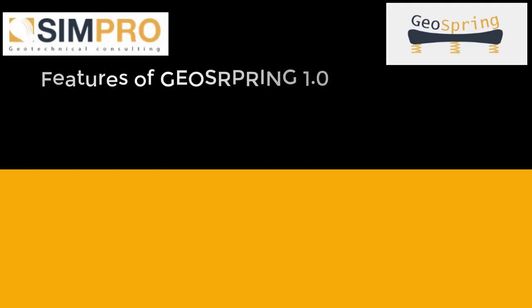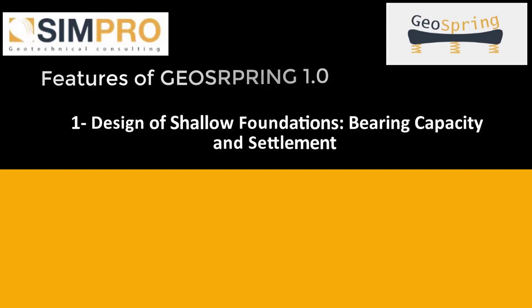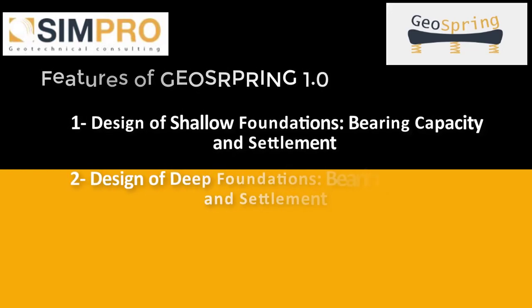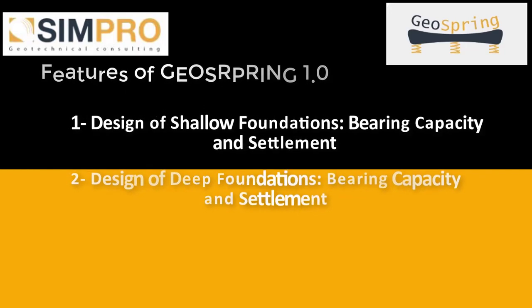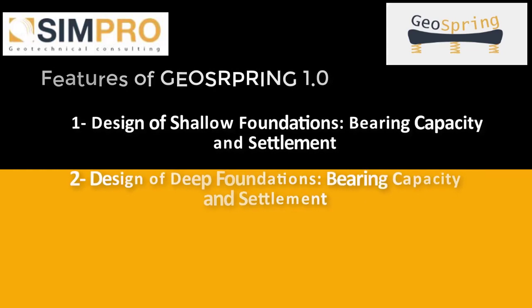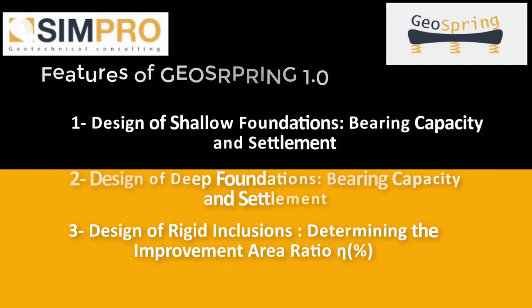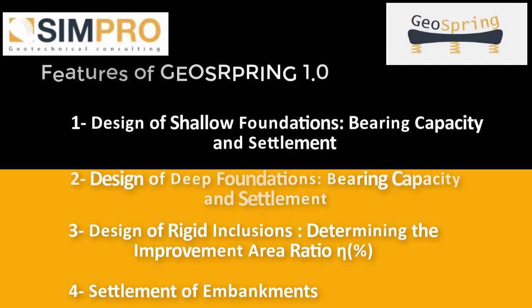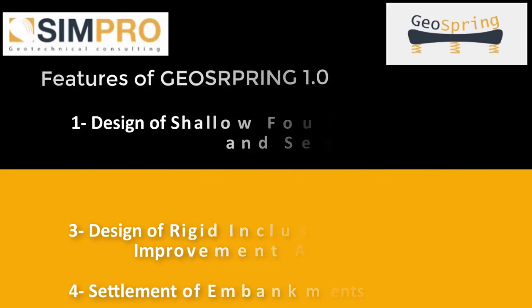Let's go ahead. Basically, GeoSpring contains 4 modules. The first module is about the design of shallow and deep foundations. It computes the bearing capacity and settlement. The second module is about pile foundations. It computes the settlement of pile foundations, single piles and groups of piles also. The third module is about the design of rigid enclosures. And the final module is about the settlement of embankments, the short-term and long-term settlement of embankments.